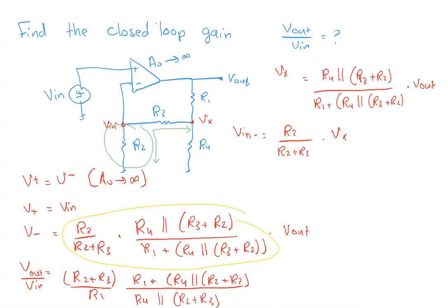So here again in this example, the trick was to find 2 times voltage divider, and then you will be able to equate the 2 terminals, and reach the gain that we are looking for. So again, R1 with R4, R3, and R2, they are forming a voltage divider. We find Vx, and then another voltage divider from Vx to reach Vn negative. Okay.